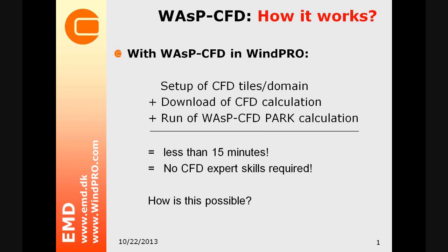Just to brush up what I just did, I've showed you how to set up a CFD domain with these 4 tiles. I outlined how to download the CFD calculation results and ran a WAsP-CFD StatGen and a park calculation. It all took less than 15 minutes, or maybe about 15 minutes, and as you saw, no CFD expert skills were really required. So you may ask yourself, how is this even possible, and what is inside the box? And this will be the topic for our next presentations.